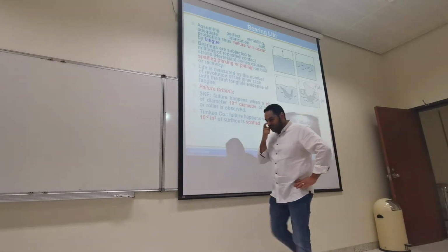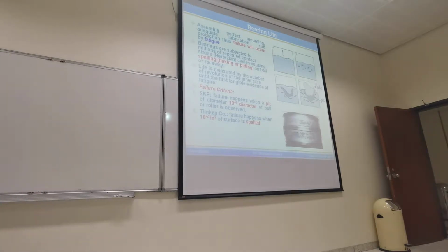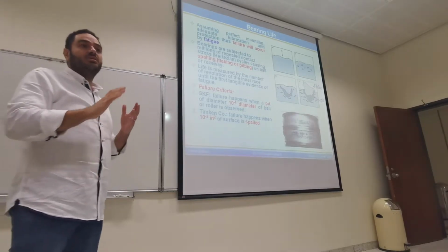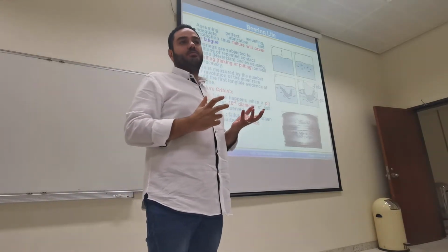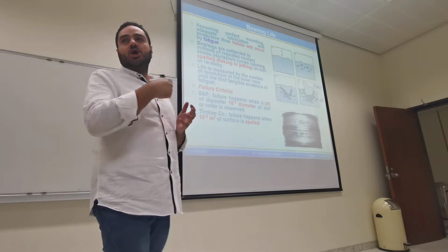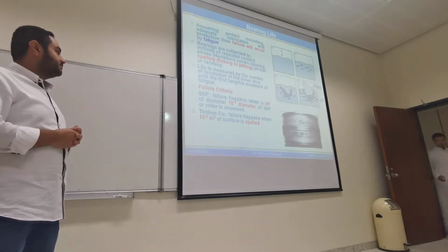Now in reality, maybe less than 10% of bearings achieve the desired life. So 10% fail due to fatigue. The remaining fail due to improper mounting, insufficient lubrication, and so on, or inappropriate lubrication, maybe using a different oil or different grease than the bearing manufacturer recommendation.